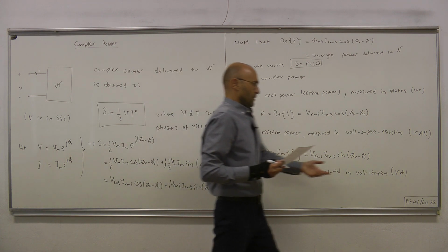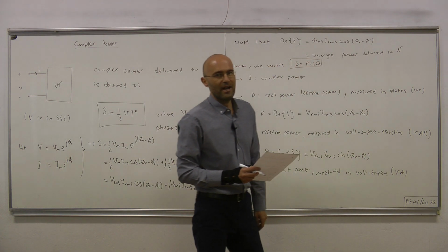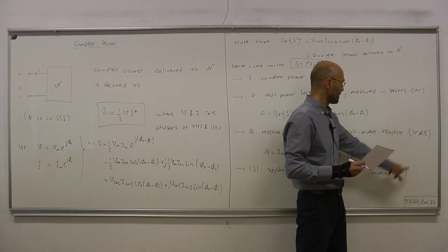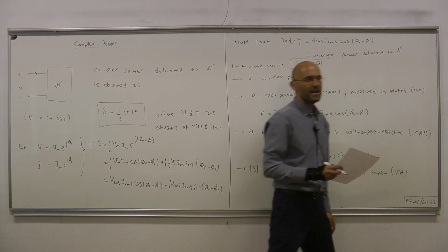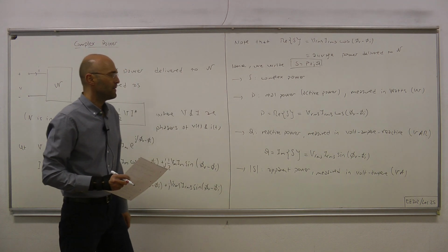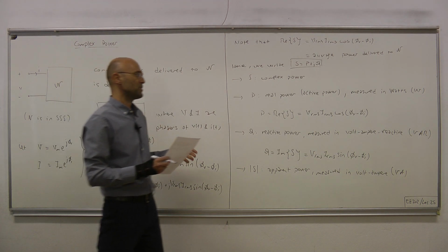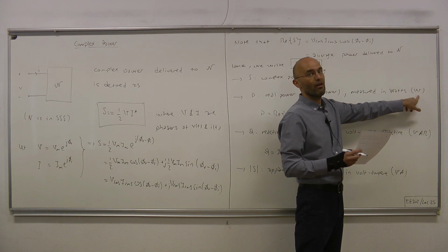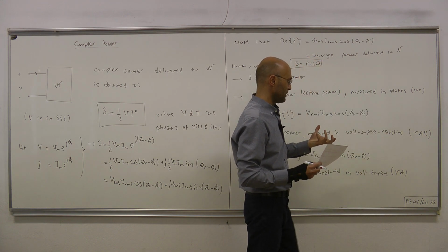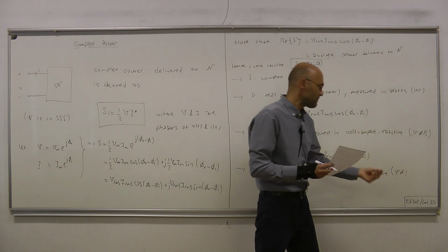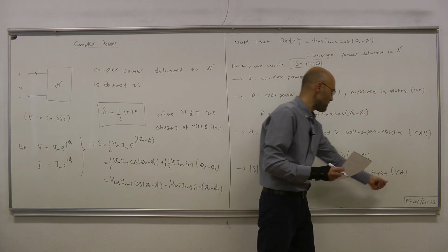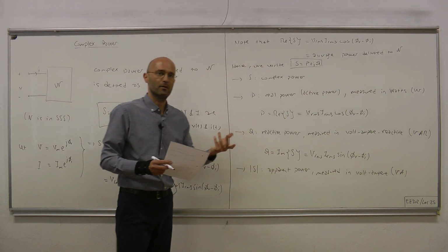Now, volt times amps is watts. So it seems like W and VA are the same thing. But for communication purposes, we never write watt for this or volt times amp for that. Because when we express something and give the proper units, that unit will tell us what we're talking about.